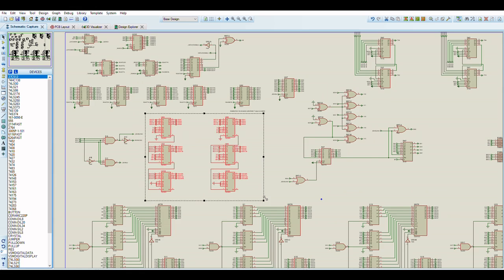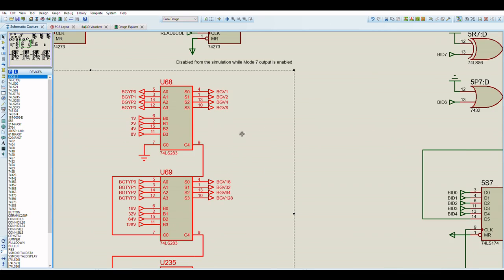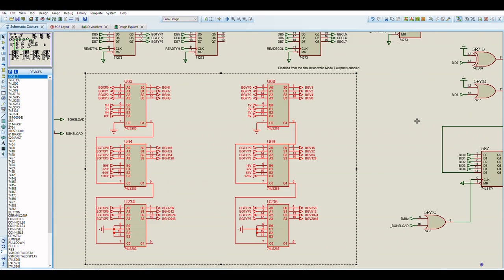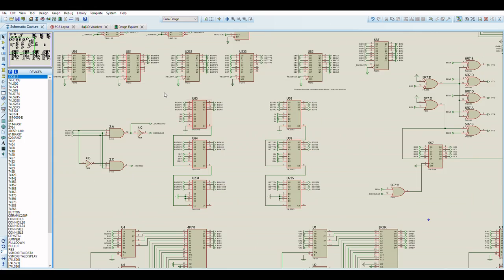This logic here calculates new values for horizontal and vertical pixel values by adding the X pixel scroll to the horizontal pixel position and the Y pixel scroll to the vertical pixel position, and then outputting new internal values that are used only by the background. This means that only the background will be scrolling around. The character screen doesn't have addition logic here.